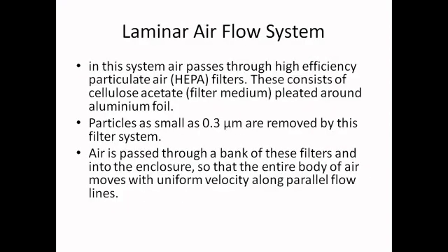The next is the laminar airflow system or high efficiency particulate air filter system, that is HEPA filters. HEPA filters are widely used to remove microorganisms in air. HEPA filters are composed of a mat of randomly arranged fibers, fiberglass filters with pore size of 0.5 to 2 microns.